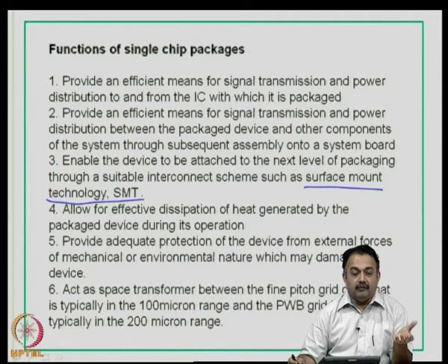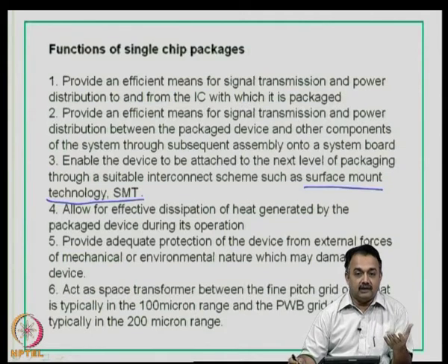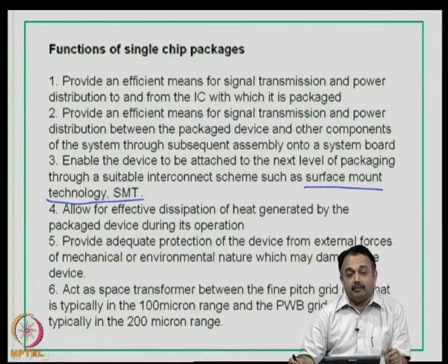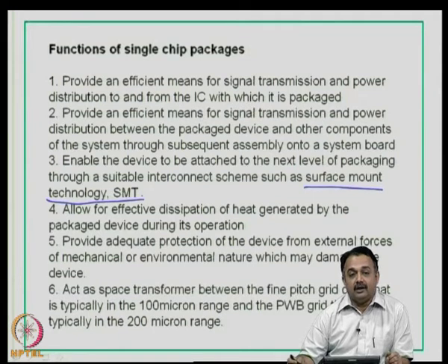And if you are an efficient designer of the printed wiring board, you will take care of heat in different ways: through the solder joint, through some kind of a heat sink or a copper plane that you have generated in the printed wiring board to remove the heat quickly. Other methods can be by using an external heat sink on top of the device to efficiently remove the heat. So, this is a very important point that you have to take care of in deciding what package you want to use.